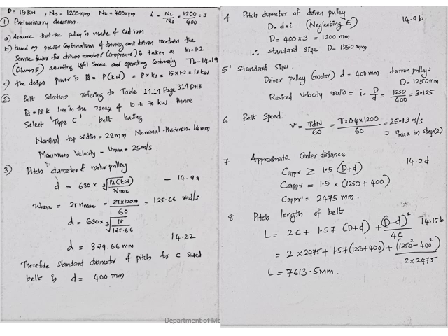And next you have to select which type of the belt. Referring to the table 14.14 of page 314 of data book, we have PD 18 lies in range of 10 to 70 kilowatt. Hence we have to select the type C belt having nominal top width 22 mm, nominal thickness 14 mm and maximum velocity Vmax equal to 25 meter per second.